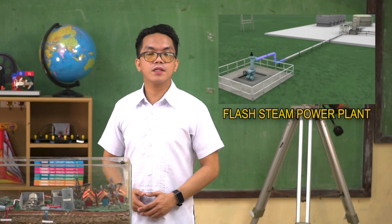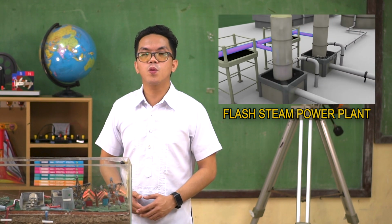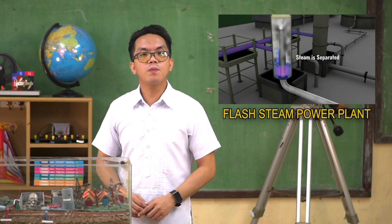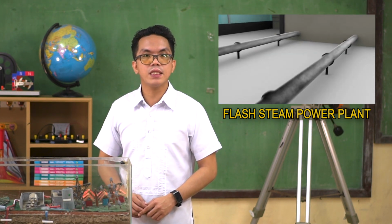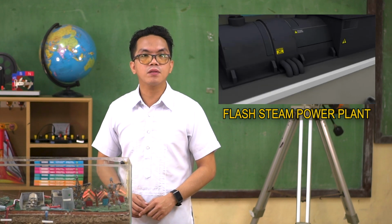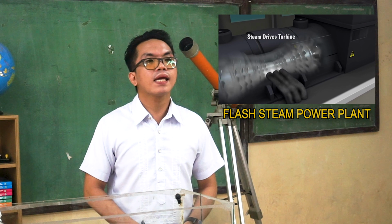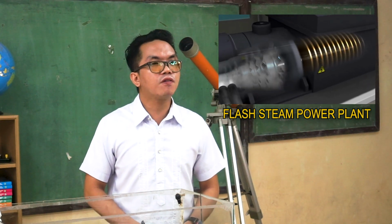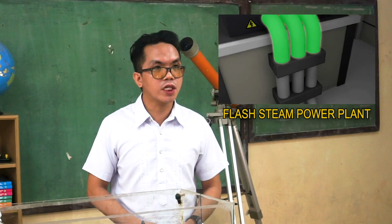Water that is hotter than 182 degrees Celsius is pumped into a low-pressure area. Some of the water flashes, or evaporates rapidly, into steam and is funneled out to power a turbine and generate electricity. Any remaining water can be flashed in a separate tank to extract more energy.